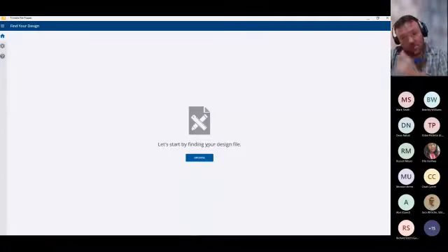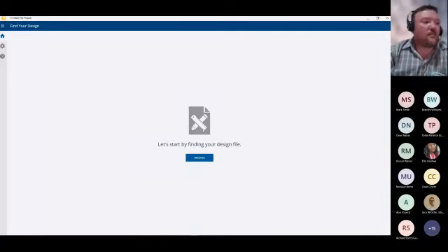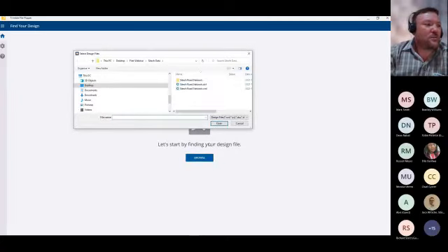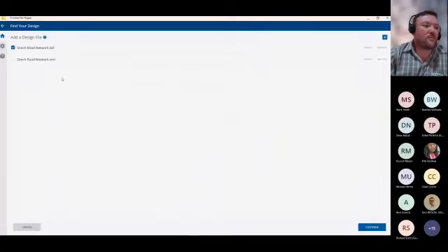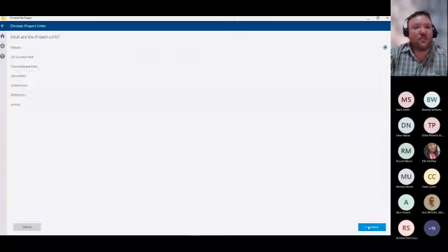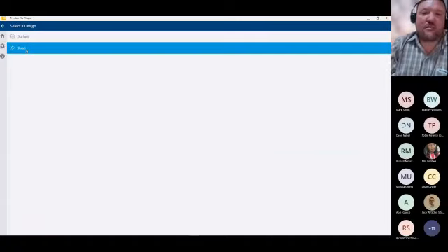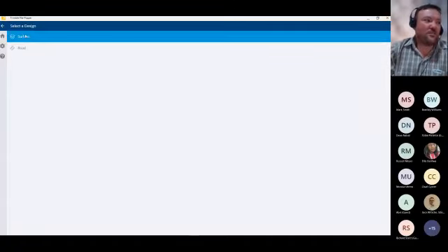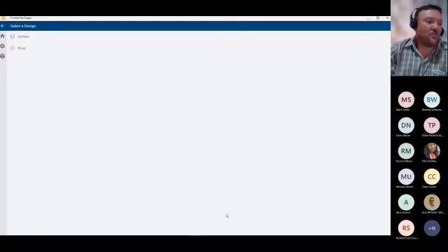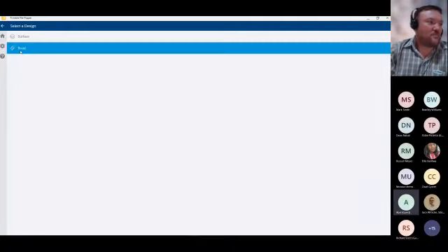Let's use the Earthworks one quickly. Again, it takes you straight back to the main page. I'm going to browse. I'm going to select my two folders again, select both files, and say continue. So just remember, we do it now for Trimble Earthworks. That's the other machine control platform. And again, meters. Now I want to do a road with the alignment. So I don't want the surface only. I want the road and my alignment included.